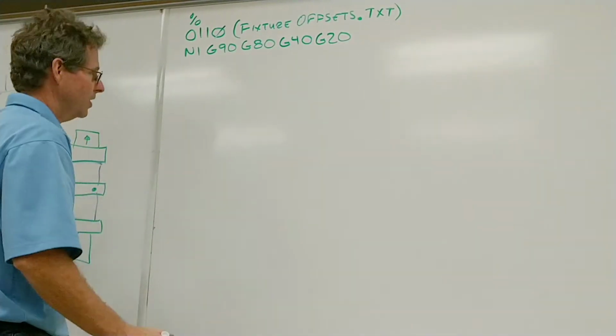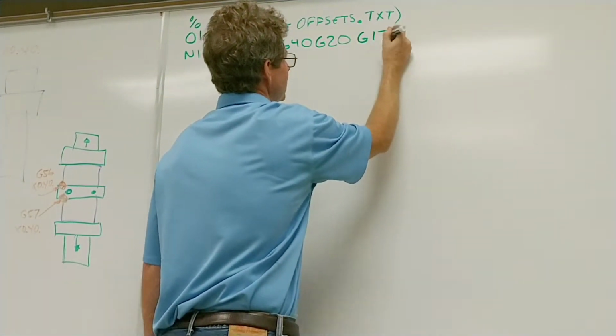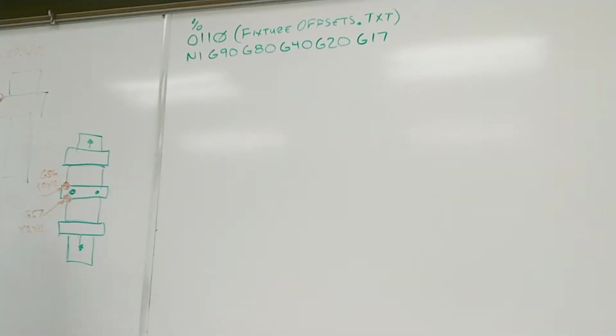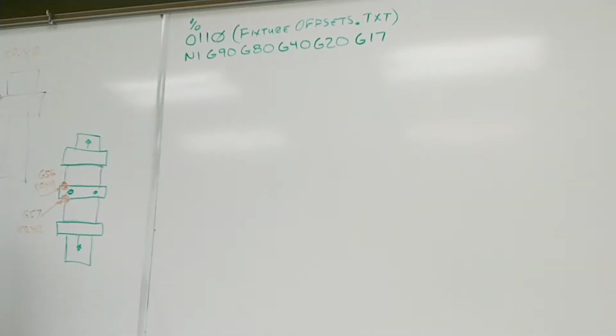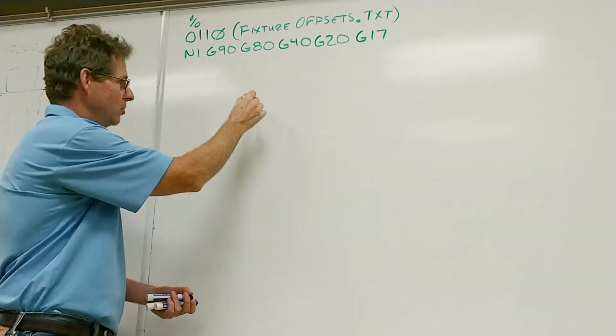And then also very commonly you see, this is what's called a set the work plane. We're setting the work plane to the XY plane. Okay, which kind of seems redundant maybe, but at the same time, I can switch my work plane to G18 and G19 if I want to do an arc going up and down.